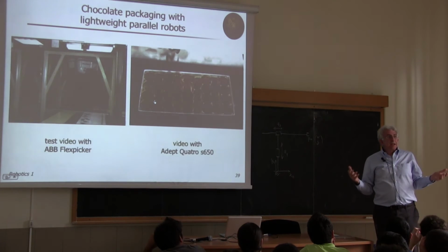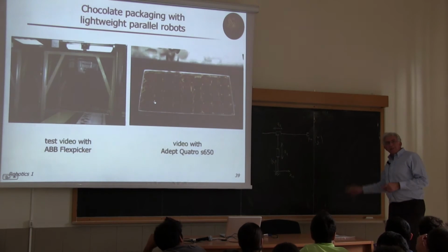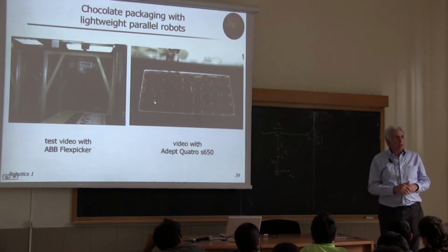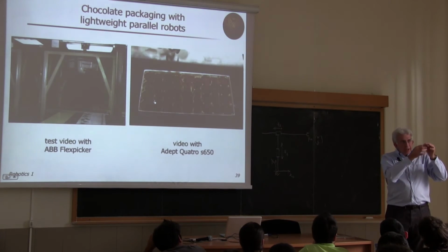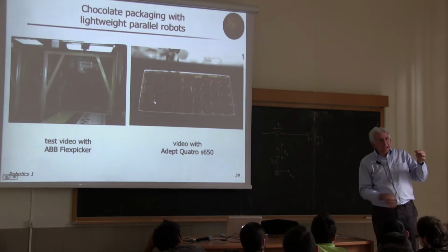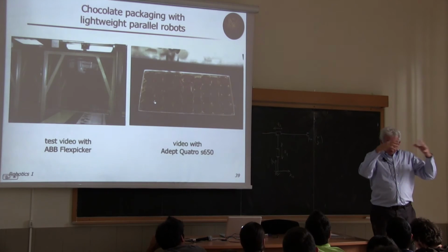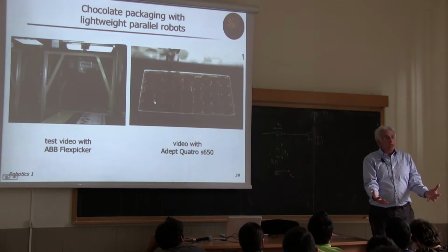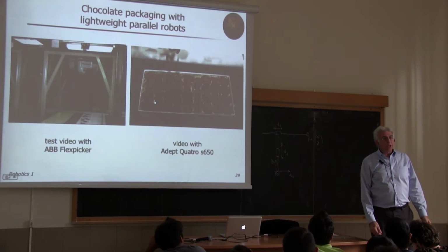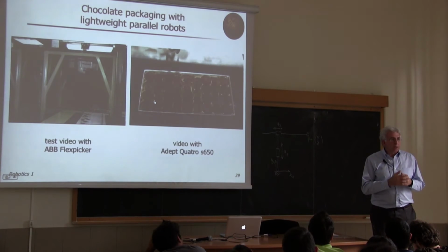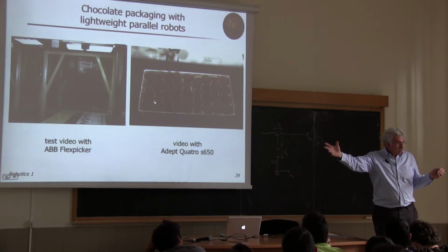It seems that these are the best of possible worlds, except for the fact that the direct kinematic is not easy. But there is one limitation, namely that the workspace is very limited. If you count the total length of the links constituting the parallel structure, and you draw the possible workspace and compute the size of this workspace, you will get a smaller workspace than if you're using this total length for building a serial manipulator structure.